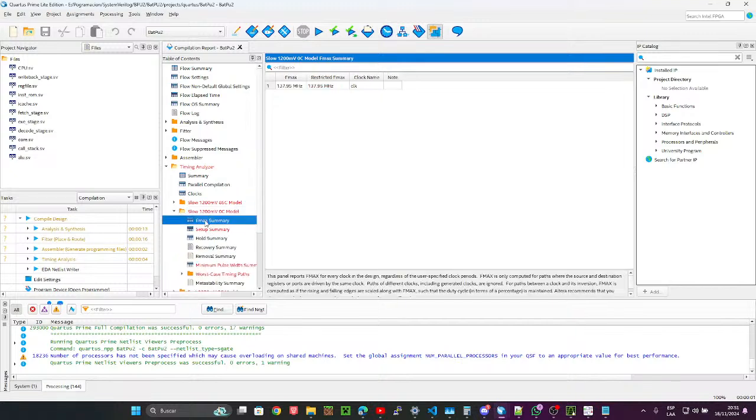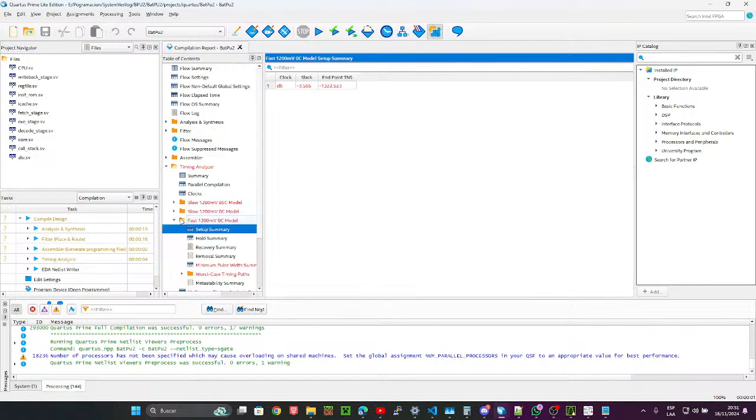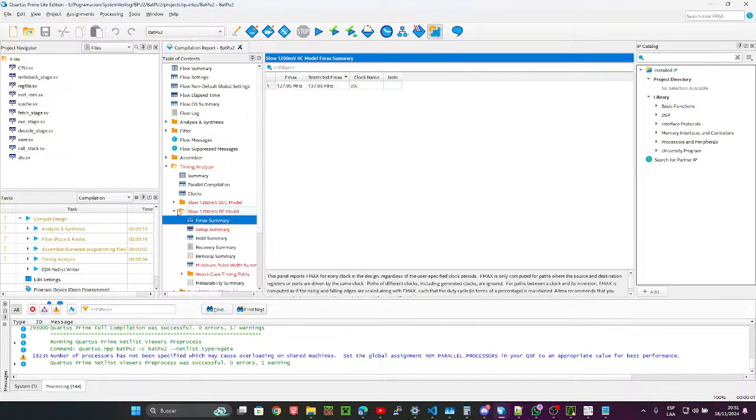Oh. You can't just take a clock and double it. You have to generate another one that's twice the speed in comparison to someone else. Which may sound the same, but kinda isn't, because you're generating a new one, you're not deriving the previous one. Yes. You're just using the other one as a reference. Oh. That's what the 50 megahertz crystal is there for.